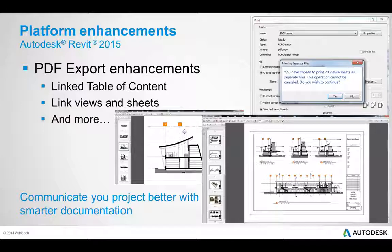All right. This one I really like, the PDF export enhancement. Now, granted, it's not like AutoCAD, which has an actual configured driver for us to create a PDF from a drawing. We're not doing that. We still need a PDF driver as a Windows system printer inside of Revit to generate that. But if we are doing so, we are exporting PDF files, whether they be individual files or as a whole file, several sheets inside of one PDF.